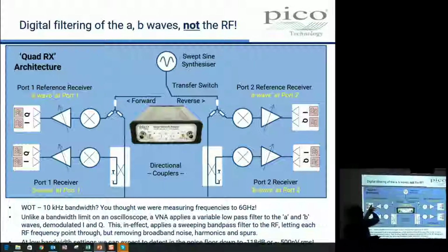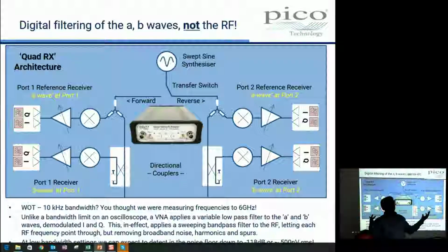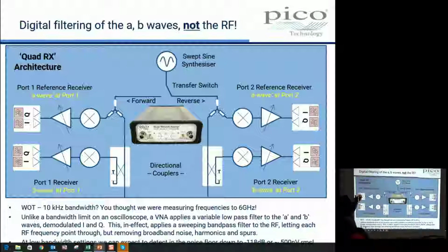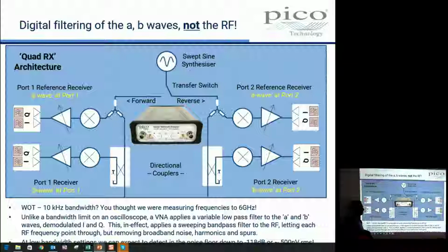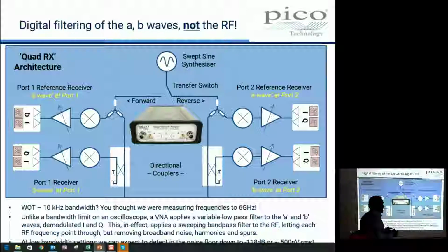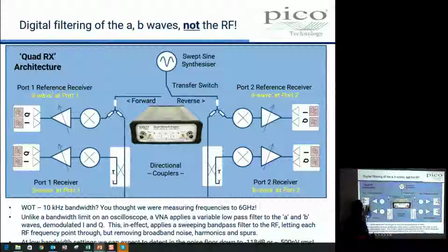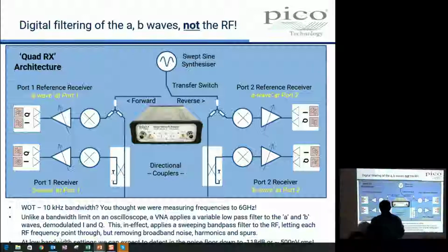And now I can process this 1 megahertz in fast A to D converters. Well, not that fast actually, 100 megasamples per second. This is an 8-channel scope, if you like. The VNA has fast A to D converters, 2 behind each channel, 100 megasamples per second, and they're capturing relatively short traces, not great big giga thingies that we do, but relatively short traces of data, and so that's an 8-channel scope at the edges there.